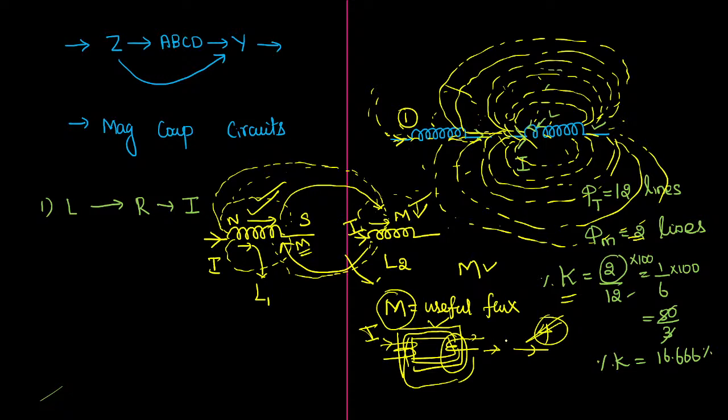Basically, when you connect a variety of loads on the secondary side of the transformer, based on the nature of the load, different amounts of flux lines will be created on the secondary side. Those flux lines will be directly cancelled or destroyed by the primary flux. So that is the operation, such that, in the resultant, because of the load there will be no effect inside the transformer. The transformer will try to maintain the same flux at all times.